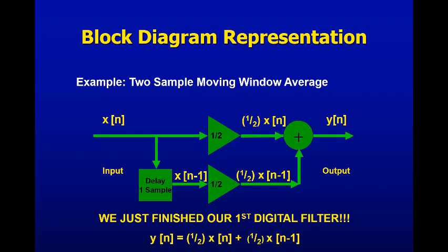And you could conceive these could be blocks of digital hardware. You probably studied in 133 or 233 how to make a digital adder. And you can gang together adders to make multipliers of digital numbers. And delays are simply memory units or shift registers. Take a sample in, wait till the next clock cycle, and shift it back out. So basically, with some memory and some combinational logic, you can make any difference equation implementation.